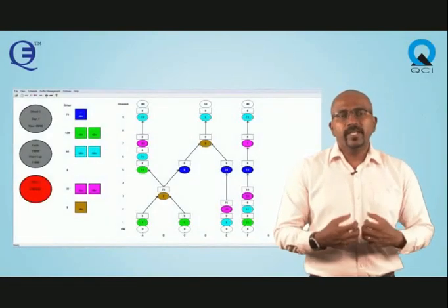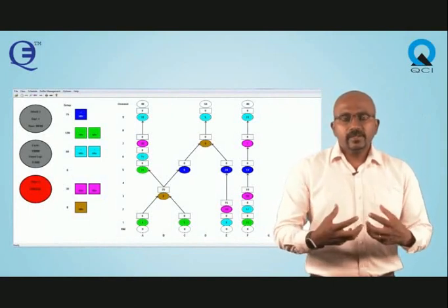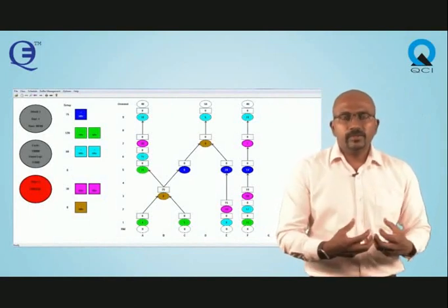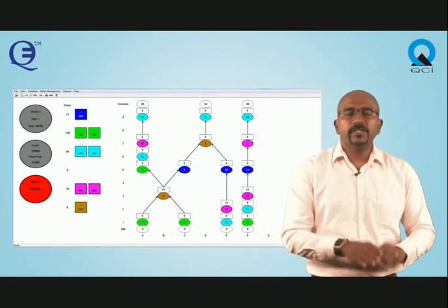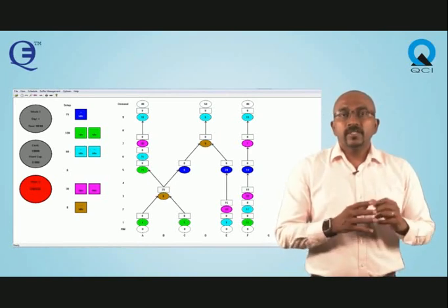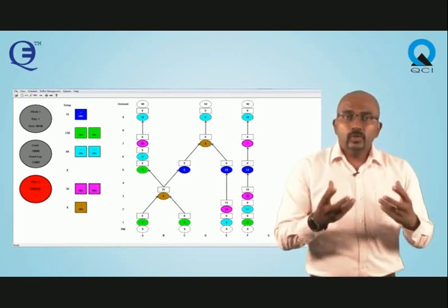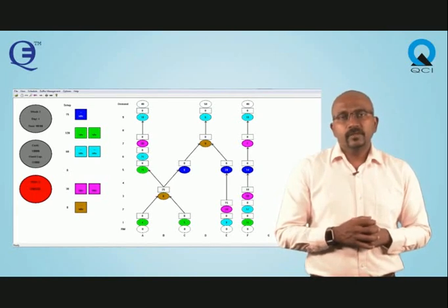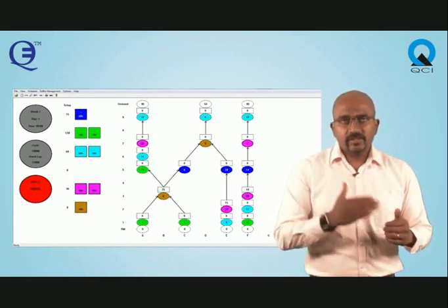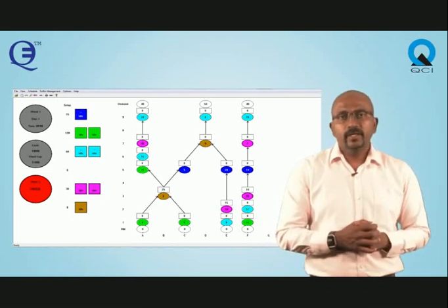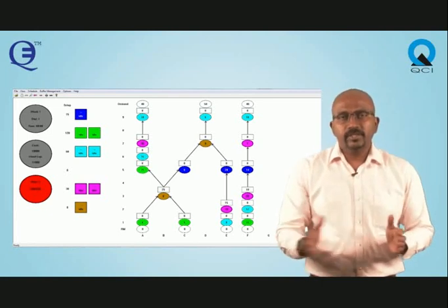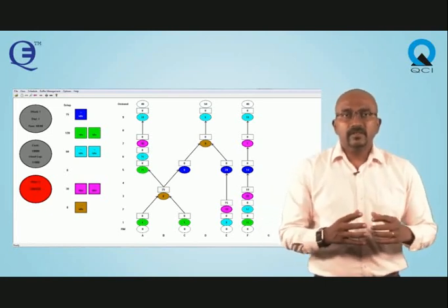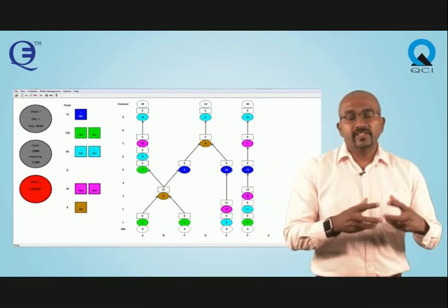But let us look at it from the operations point of view, shop floor management. It seems that it is the brown resource which is used one after the another. That means there's a material coming back for operation on the brown resource. Now, since one resource is used for two operations and at different stages of operation the same resource is required, this means that there's a feedback loop, or there's a loop in production process. Now this does make manufacturing complicated.